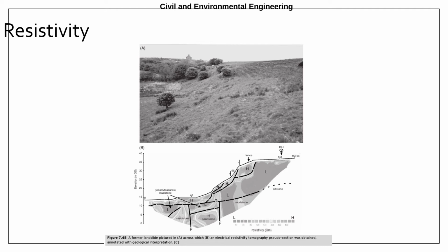And my disclaimer here, as someone who's been working on landslides for almost 10 years, is that you can't always apply resistivity on landslides, because resistivity depends so much on groundwater, and there are so many types of landslides that you can encounter.